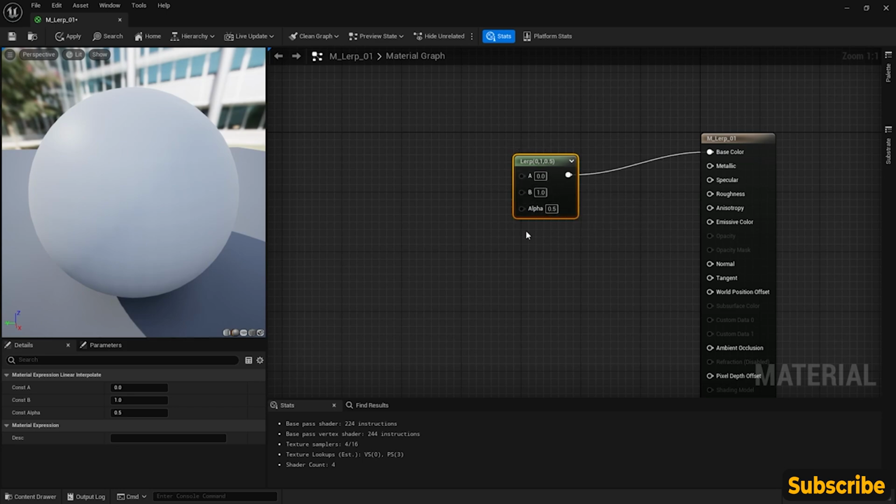But basically what this node is saying is, let's blend between whatever's in A. So again, 0 is black. And let's blend with whatever's in B, pure white, by a percentage. So the alpha here will be a 0 to 1. So at 0.5, we're 50% in the middle of these two values. So if I want to see whatever is in A 100%, I need to set my alpha to 0.